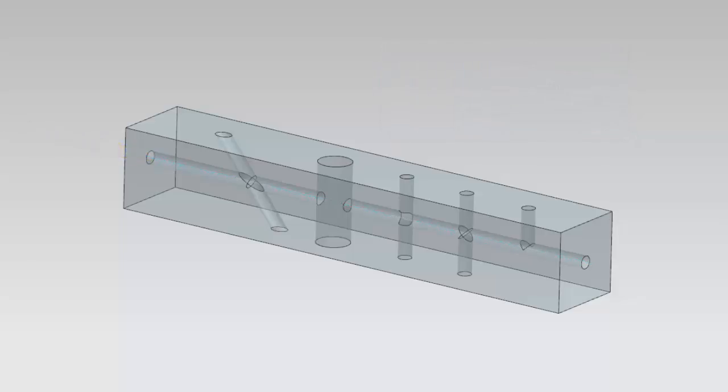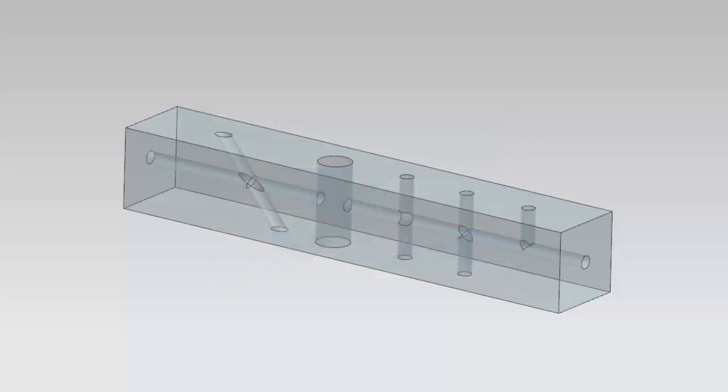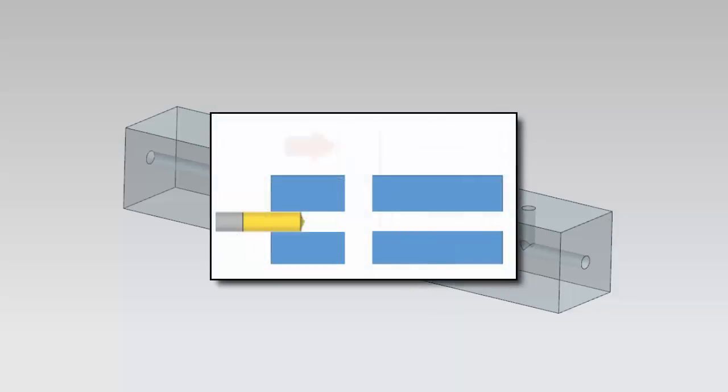Sequential and deep drilling operations identify intersecting holes and apply cutting and non-cutting feed rates to each drill cycle. If the intersection is greater than or equal to the specified crossover distance, NX crosses the intersection with three motions using last cut, crossover, and first cut feed rates. If the intersection is less than the specified crossover distance, NX crosses the intersection at the stepover feed rate with a single motion.